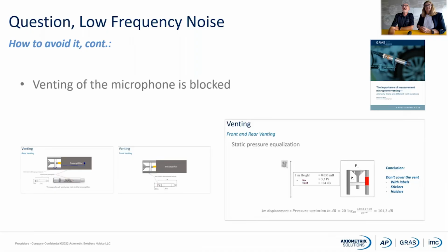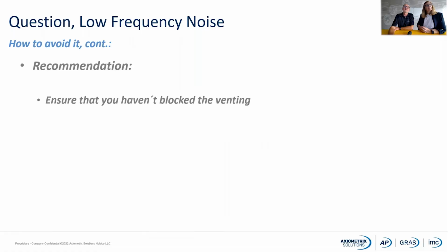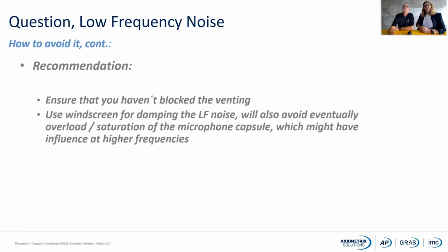We do have an application note describing this little issue, and it can be found on our website. So my recommendation is, first of all, ensure that you haven't blocked the venting system. Use a windscreen for damping the low frequency noise.